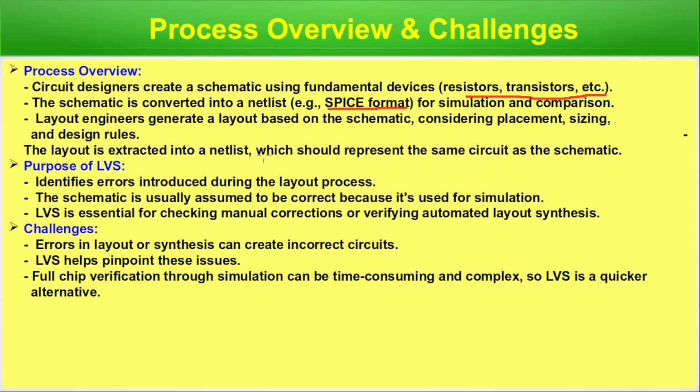Now the layout engineer generates a layout based on the schematic, considering placement, sizing and design rules. The layout is extracted into a netlist, which should represent the same circuit as the schematic. So one netlist we get from the layout, and another is from the schematic. So we have to compare these two. Purpose of LVS: identify errors introduced during the layout process.